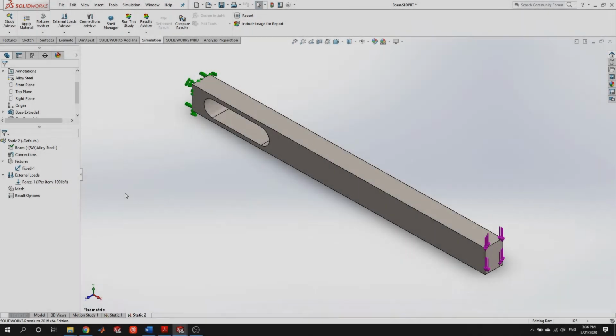All right, we've now seen how to perform a basic simulation in FEA and in this SolidWorks FEA environment. So remember, the first thing we need to start with is our geometry. If we have a large, complex part or assembly, we often want to figure out how to extract a part of interest. Maybe if we had a car, for example, and we're interested in the suspension, we want to extract just a single rocker arm and do the simulation on that. We'll have a lot better results. We'll have a lot easier time getting this to work, especially at the beginning while we're learning this.